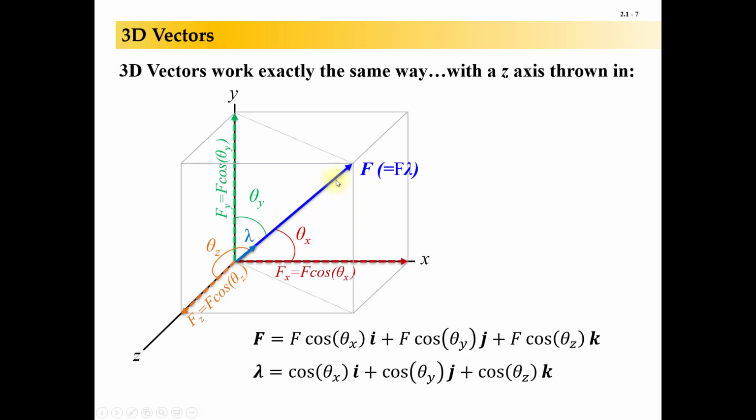So if this vector is coming out into the positive x, positive y, positive z portion of space, like it is, theta x is swinging from the x towards us and up at the same time to get up here. And theta y is swinging towards us and down. And theta z is swinging away from us and up. So they're a little hard to actually see in real life, but they're not any harder to deal with on the page once you have Cartesian vector formats.